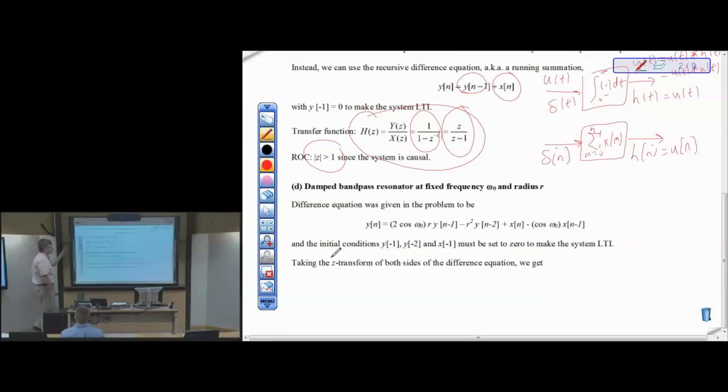Now, the integrator is the dual of the, what kind of filter is this? Well, the problem is it's not BIBO stable. So it's a little bit more complicated here. If you exclude zero frequency or very low frequencies, you get a low-pass response. The unboundedness happens at zero frequency. So the running sum is useful usually after you apply a removal of DC. If you remove the DC component, then do the running sum, you're safe in terms of stability.